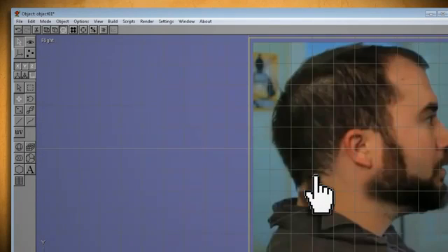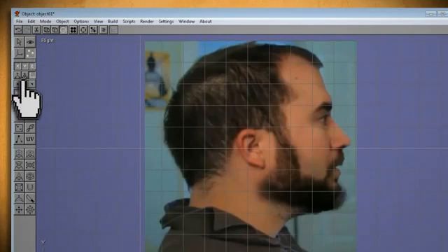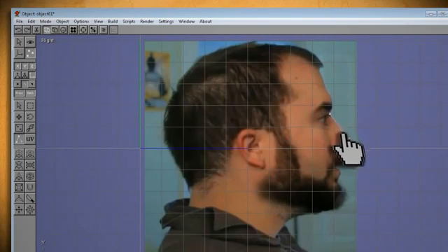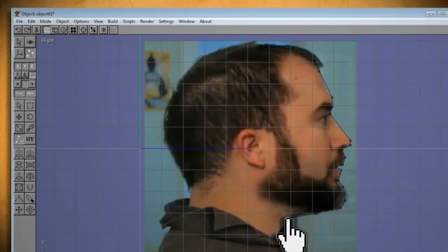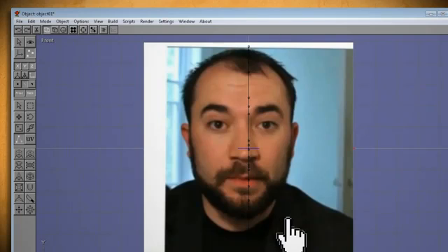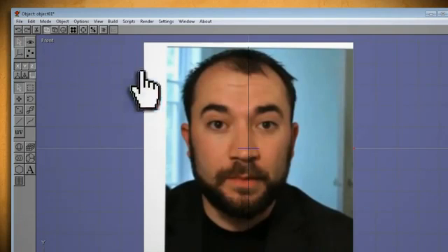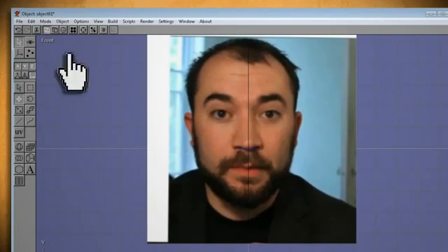Switch to either side views and click on the Point Editor, Edge Select and Add Edge buttons in the toolbar. Hold down the Shift key and, starting with the nose, click and drag a line along the contour of it. Now just click on either side of that line to start another line. Continue this until you have the whole front half of the face outlined. Switch to the front view and you should see the line that we just drew directly in the center of the picture. If it isn't, move the picture so that it's centered with the line.